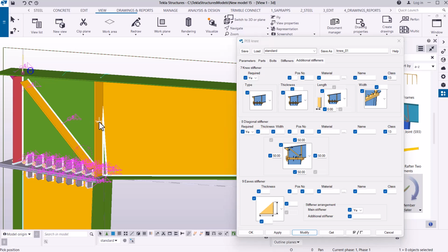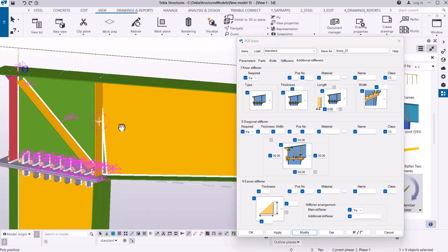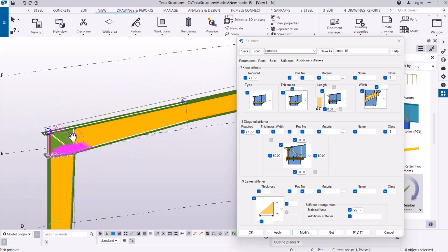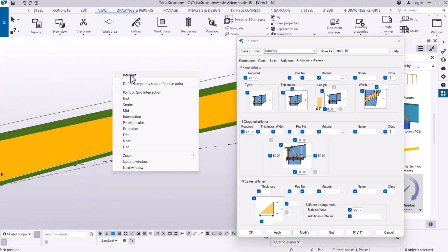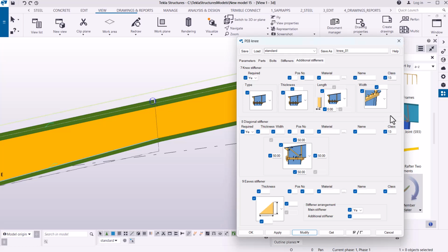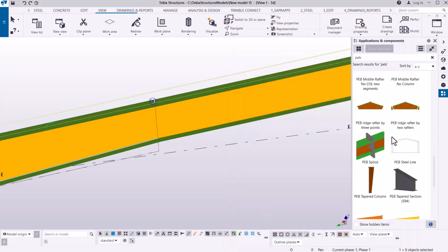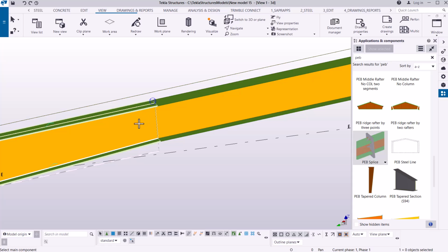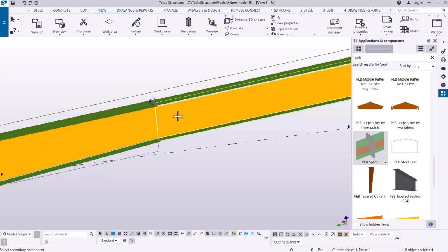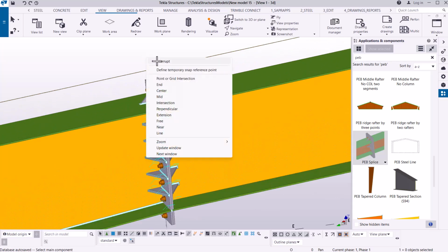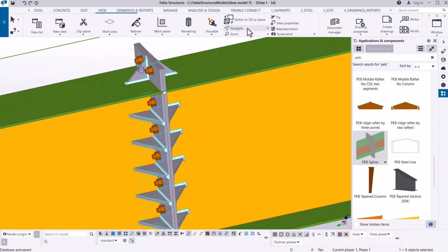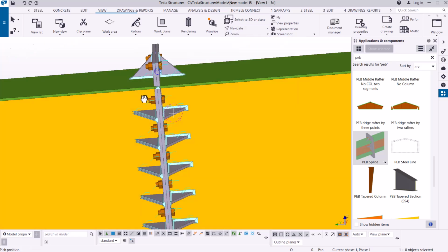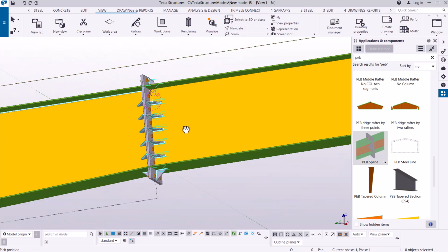Once you've done so, what I'm going to do next is to complete this stiffener here, this splice. So this splice is very easy. I'll close this, then come to splice. On this splice, pick the main component is this, and the secondary component is that, and I'll just give some time to load that information, and boom, we have this in place. We've created a splice between these two rafters.